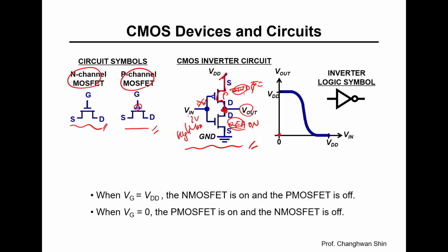So this complementary behavior is why modern processors such as CPUs can pack billions of transistors onto a chip without melting from heat generation. Only during the brief switching transition do both transistors conduct simultaneously, making CMOS technology the foundation of energy efficient computing.